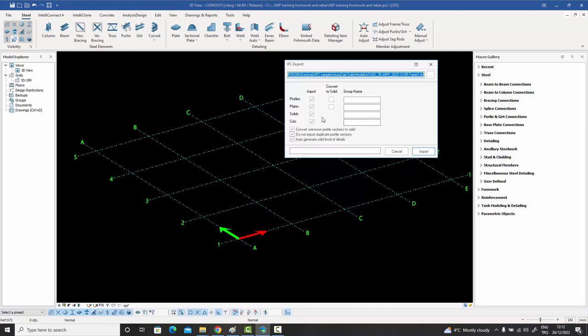So what that means is that sometimes you have generic solids which are very complex, and they have literally thousands upon thousands of polygons, and they make your rendering experience a little less enjoyable. And in those cases, what you can do is auto-generate the solid level of details, and it'll make the rendering faster.